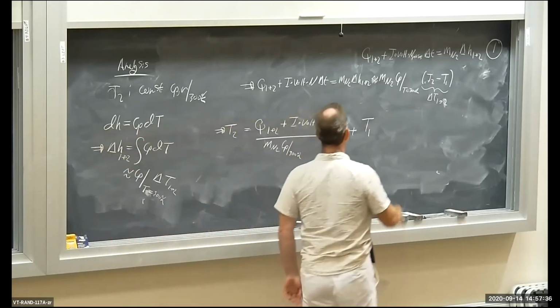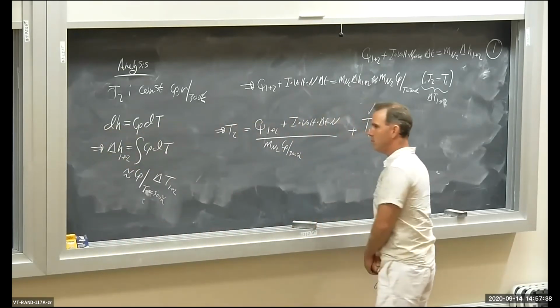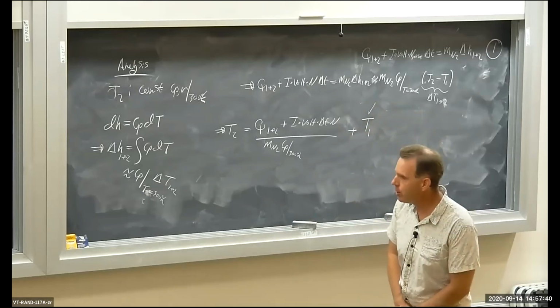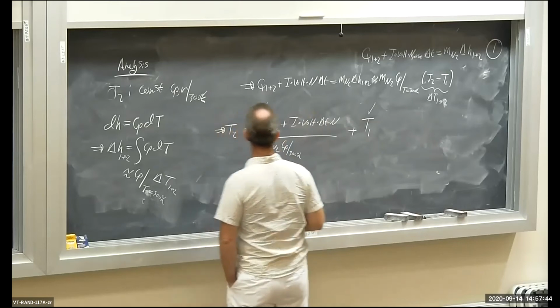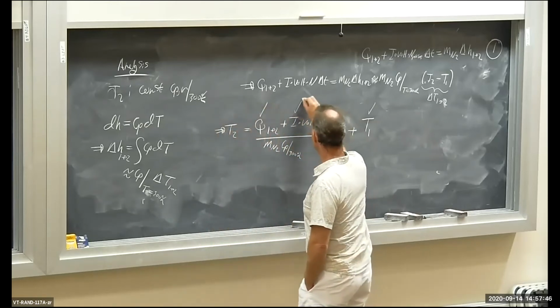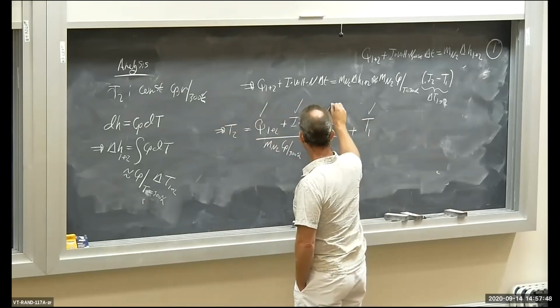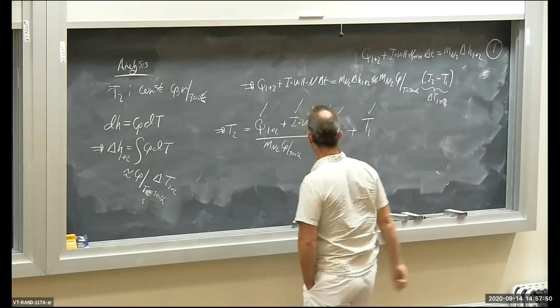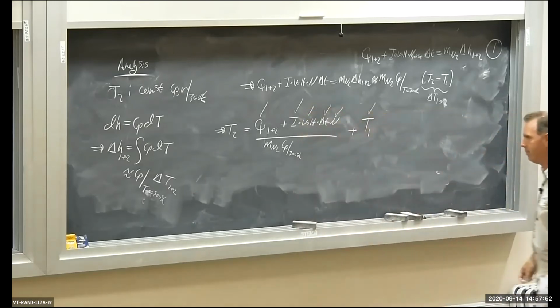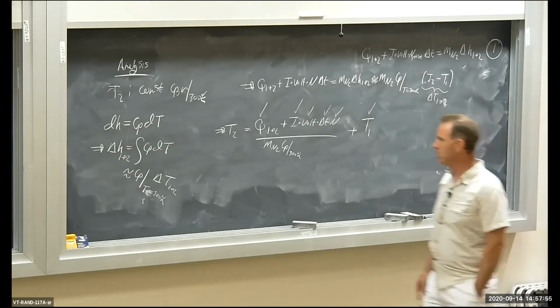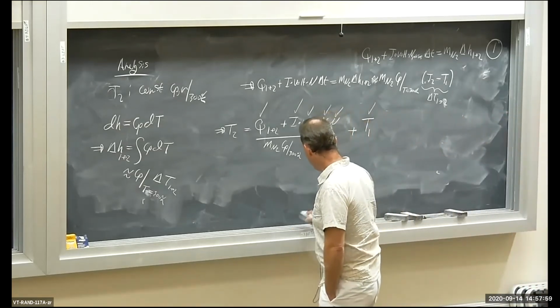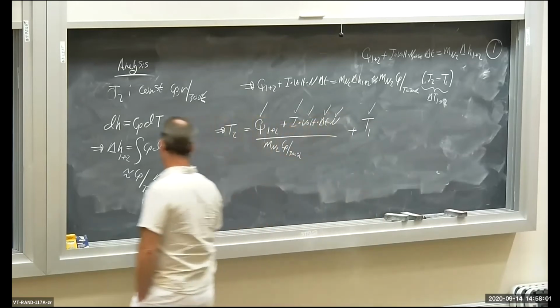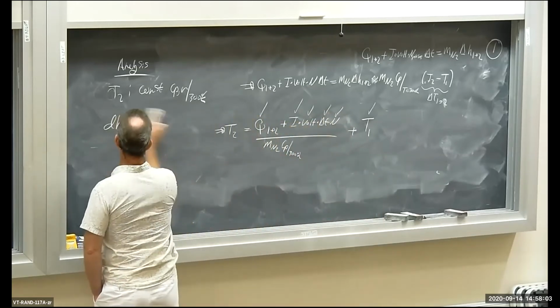Well, I got the original temperature, 27 degrees C. I have the heat transfer. I have the current. I have the voltage. I have the time, 60 seconds or 1 minute, and I have the number of resistors. There are 5 of them. I don't have the mass of the nitrogen, and I don't have the specific heat at 300 degrees Kelvin. Let's calculate those things.